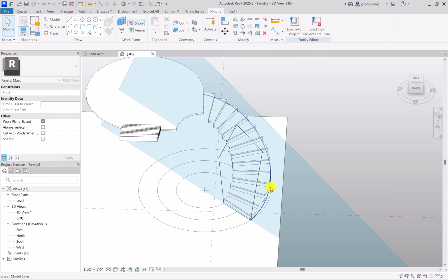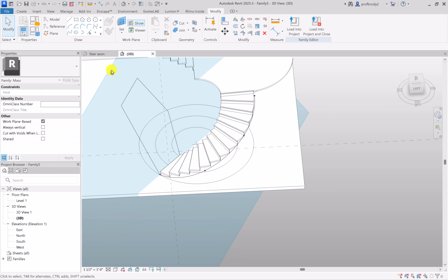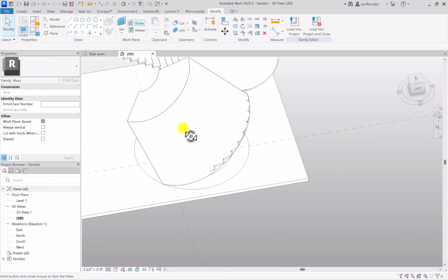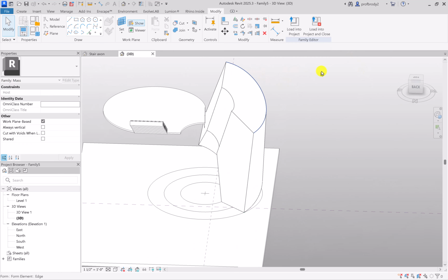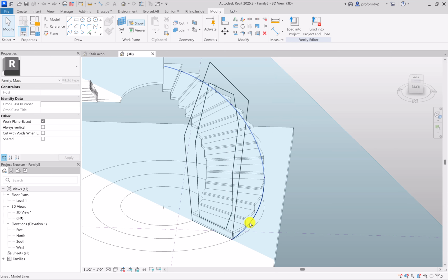If I select that shape and the curve that I just drew, let's see if we can get a view where we can do that, and I'll just use a selection window. It should create a form of that shape, right? And that is pretty cool. And if you wanted to void out the middle, and I created a second profile here that's even more wacky than the first, you can do that.